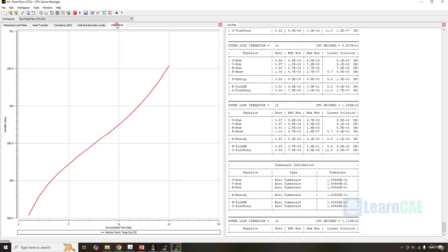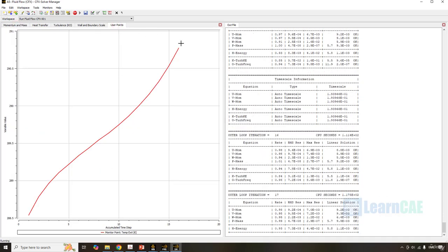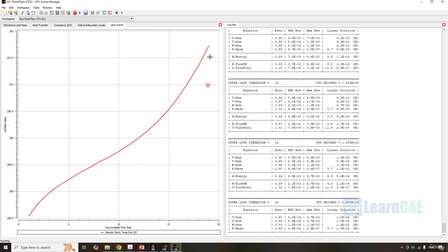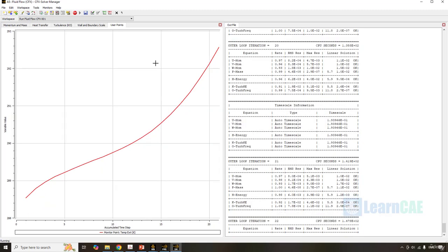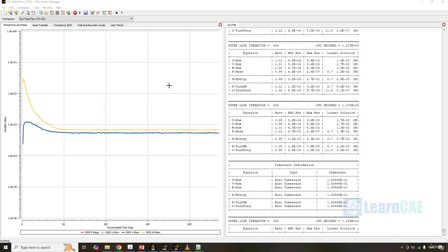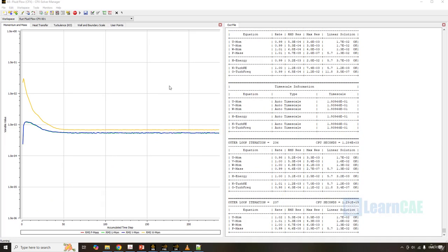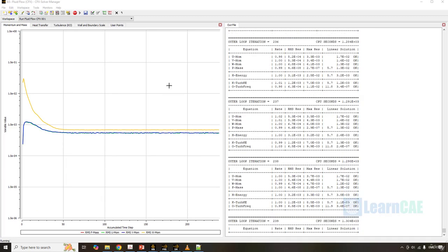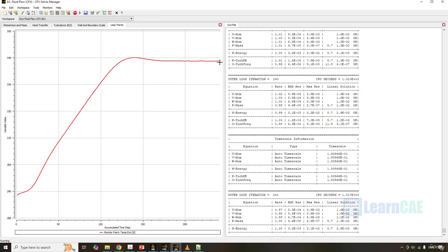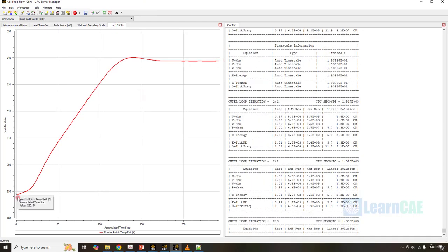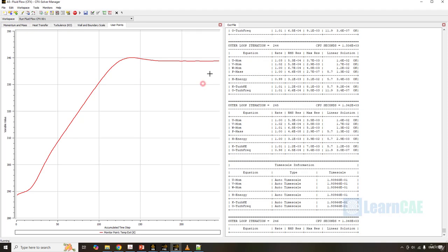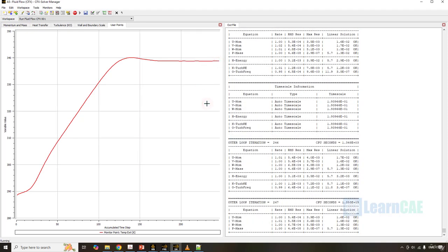If we come to the user points, the expression that you have created is shown here. We can see the exit temperature, it is getting increased. It will converge after a certain number of iterations. Okay. We can pause and come back after a while. If you see here, the residuals have become almost constant beyond a certain number of iterations, and when we check the exit temperature, it has become almost constant. So it started from 288 Kelvin and it has finally reached 338 Kelvin. It is almost flat. So we shall not run beyond this.